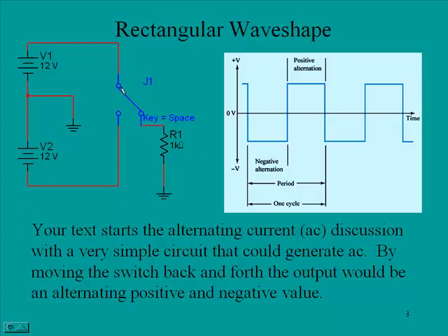Now, when we pull the switch down and it is connected to this point here, across here, notice now we're connected to a battery, but we're connected to the negative side, and so current is going to flow again through here. Now it's going to go across the switch because it's pulled down now. It's going to go down the resistor, and then it's a little bit confusing. It looks like a figure 8, but this would be the path for current. The difference here is that the current is flowing down through the resistor rather than up. In this particular configuration, that is where we're going to be generating the negative part of this square wave.